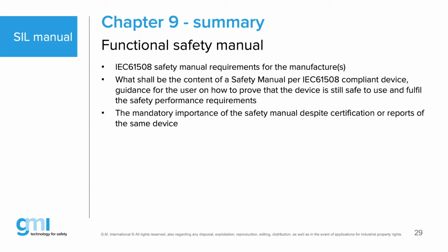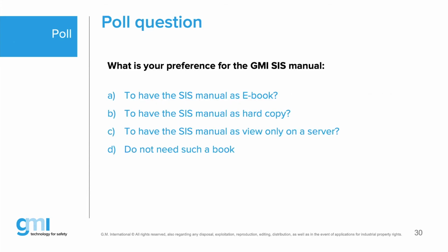The functional safety manual that I will talk about in the webinar is both. It's this one plus the new requirement from edition 2 of the 61511, which means the 2016 release, which now requires a functional safety manual on system application level. And that's a whole different story, but I will save that for the webinar.